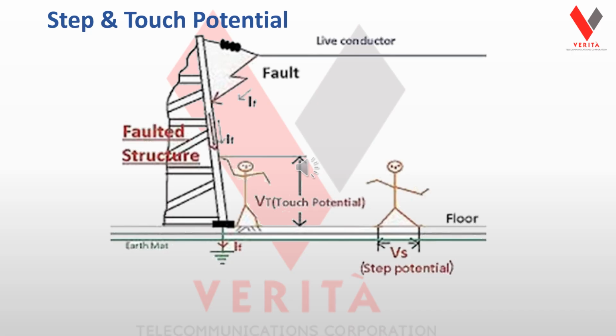If we take a look at the person in that center picture, he's actually making contact with that tower. In this case, yes, it's already grounded, but now he becomes an auxiliary path. He's another way for that current to go at a little bit lower resistance. The ground under his feet is not as saturated, so he gets shocked.